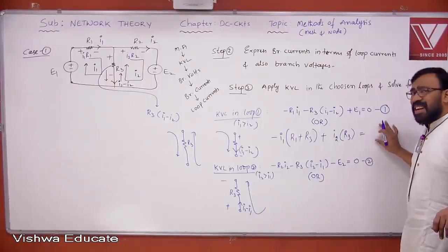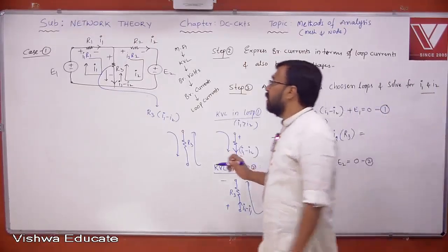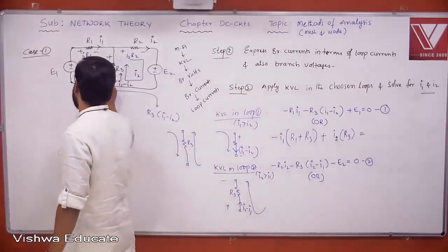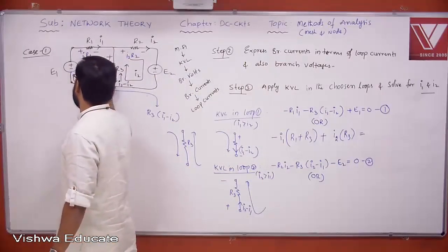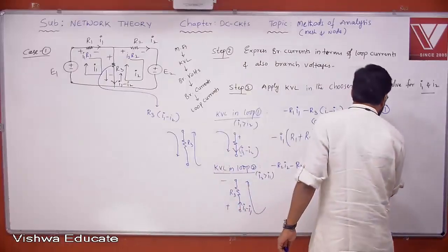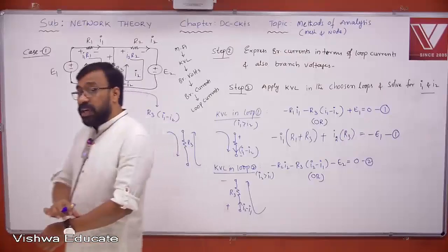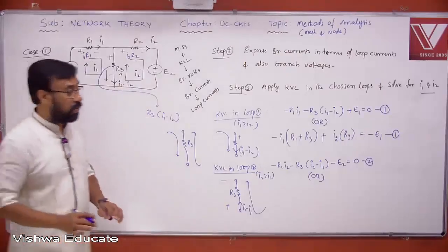Now, are there any energy sources in the first loop, particularly voltage sources? Yes, there are. How is the loop current touching the polarity? Negative sign first, therefore minus E1. That's it. Negative sign first, therefore it is minus E1. Understand all of you? Okay.